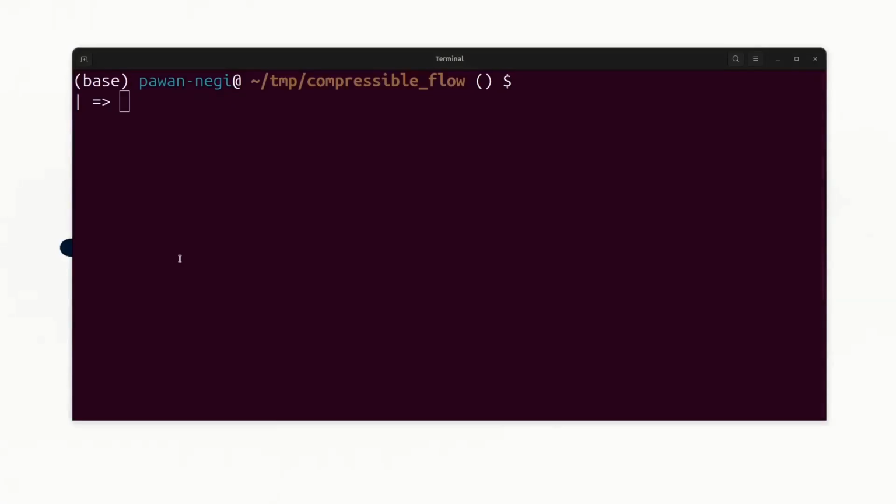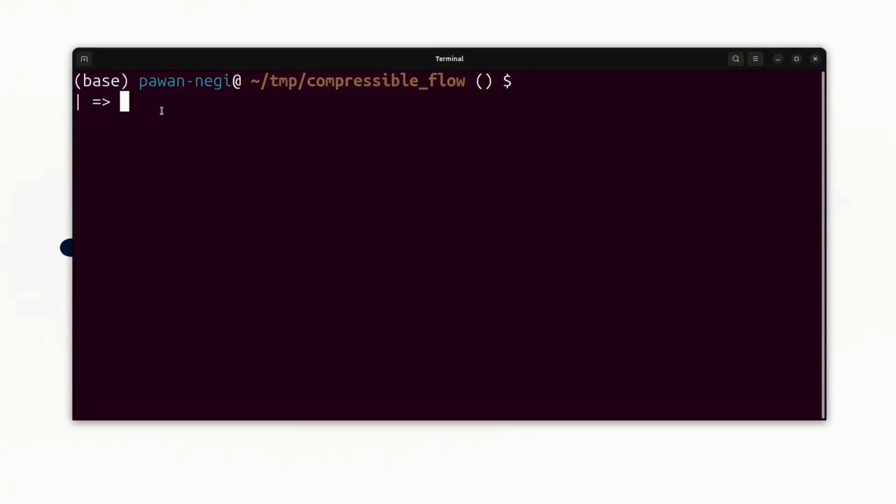Hello everyone, welcome back. In this lecture, we are going to talk about the very thing that we were talking about in our last lecture, that rhoCentralFoam does not work well when the mesh is non-uniform. That means it abruptly changes the resolution, similar to the mesh that we get from snappyHexMesh. Let me show you by copying one of the examples present in OpenFOAM tutorials.